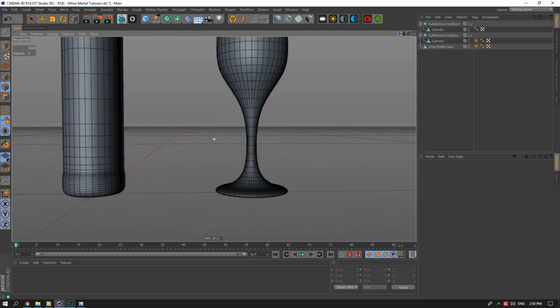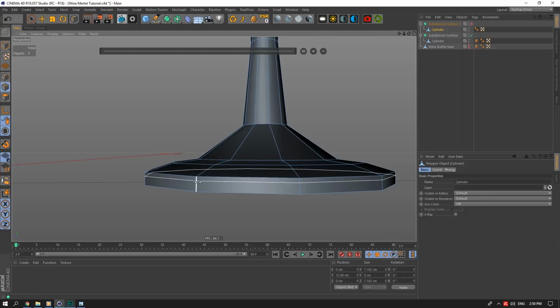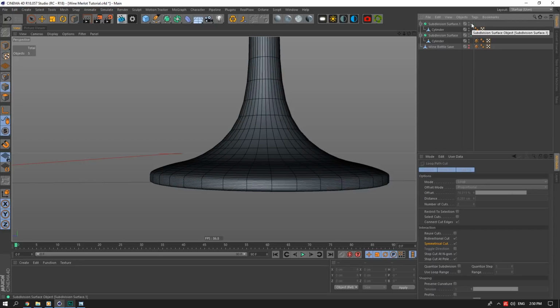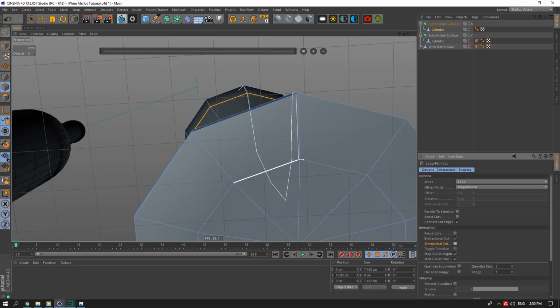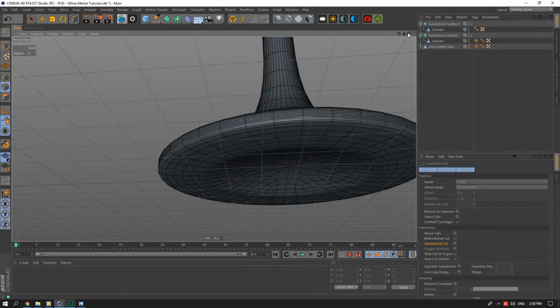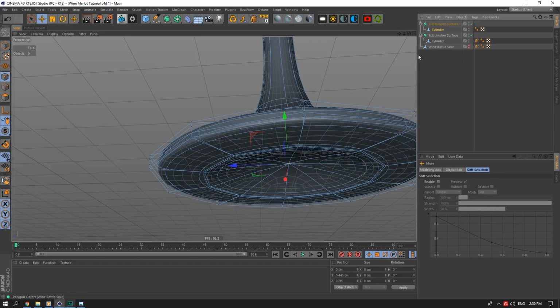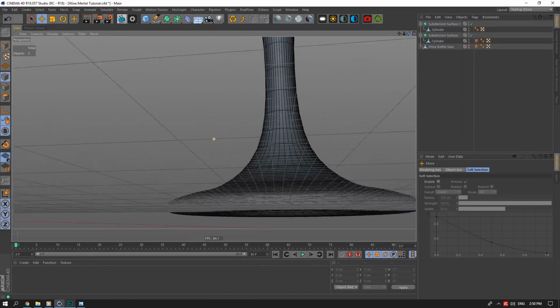If I take a look down here, it's quite accurate, but this thick part here needs a bit more support. So I think I'll put a symmetrical line inside here, something like that, and take a look. Yeah, so it's not really curved, it's a bit flat, and that's why I'm going for 2 lines instead of 1. And then inside here, we need another line to help make sure that this is also flat and not smooth, like so. Yep, so that's around what the real one looks like, but I think this should be pushed up a bit more. So like that. All these little bumps and curves will help with the reflections in our final render.